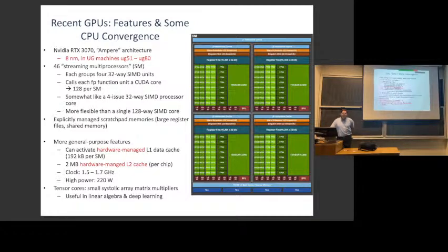There are 2 threads in the hardware on 1 core that it can execute. It can actually be interleaving instructions from both of those in a single cycle. Okay, so I actually have to change this slide. This isn't even quite right. It's basically tagging the 2 streams and able to send them both in at the same time, some instructions from each.